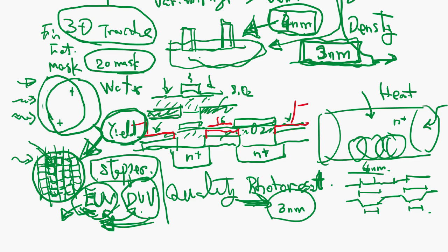Okay, so as a summary, when you talk about the size of a transistor, this definition depends on the company. It's all different. They want to talk about density, because even if the transistor is very small, if the minimum metal size is large, then the density is low because of the restriction on the metal size. You know what I mean? So density affects the die size.